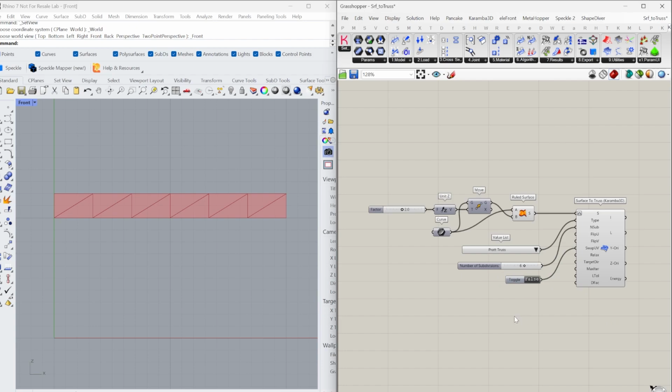The input relax angles adapts the position of the cells so that the angles between are as large as possible. If this option is disabled, the nodes on the upper and lower boundaries are positioned at evenly subdivided U values. If the vertical posts of the truss require a predefined direction, the corresponding directional constraint can be specified here at target direction using a vector.